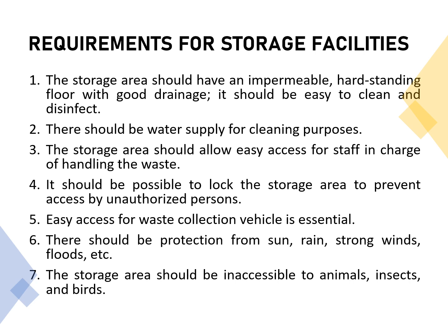Number three, the storage area should allow easy access for staff in charge of handling the waste, and he or she has the key to gain access into the storage area. That's why in number four, there should be possibility to lock the storage area to prevent access by unauthorized persons. Number five, easy access for waste collection vehicle is essential. The storage area is where the collection vehicle will get the healthcare waste to be brought to the landfill, sanitary landfill. And number six, there should be protection from sun, rain, strong winds, floods, etc.